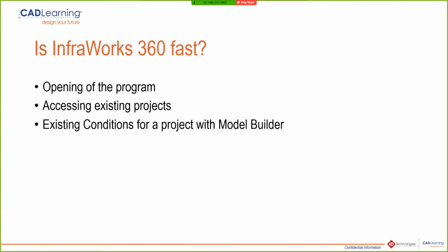The other thing to note is files in InfraWorks 360, you can't save. You can duplicate, but they're always saving. Every time you make a move, they save that move, okay? So it's constant saving, and there's no save as feature, because that's how SQLite works. They don't work in DWG format, they work as SQLite. So it's constantly updating. Every time you make a move, it saves.